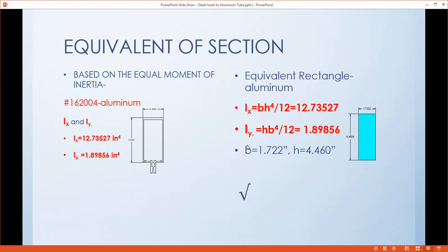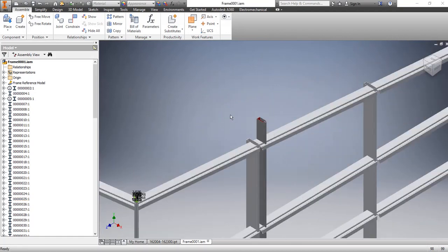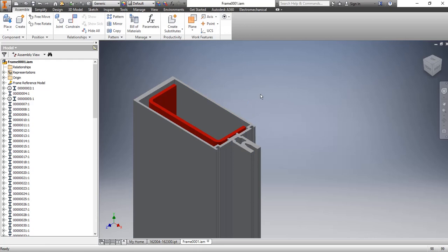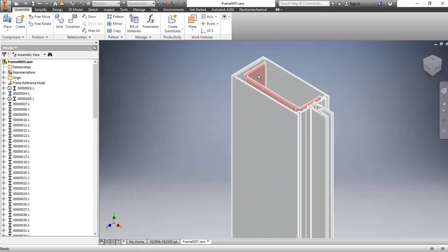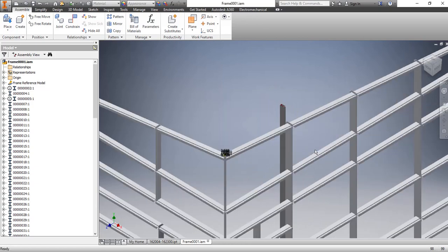What are we going to do? We have to insert steel or choose bigger back sections. For example, with this insert steel molding, the back section is the same, but we insert steel to make it stronger, so we can build the frames as tall as about 20 feet high and hold the glass.